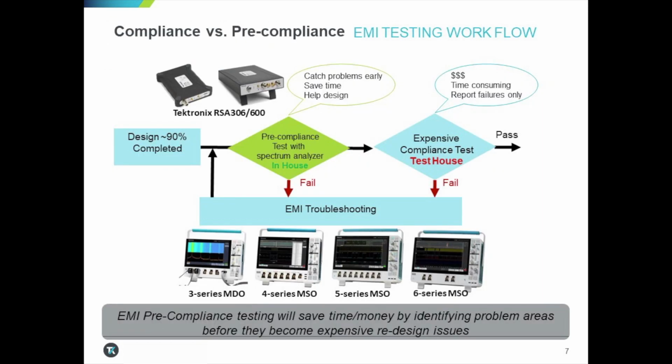Here's a simplified diagram of the typical product development cycle. Due to the lack of knowledge of EMC principles among junior engineers, many teams will often go 90% of the way and then begin to think about compliance testing. This is really incorrect and costly thinking. Compliance testing should be considered early in the development with all the risks identified early, test plan outlined, with periodic diagnostics testing, troubleshooting, and standards testing for intentional radiators, as well as pre-compliance scanning in-house throughout development of the product.